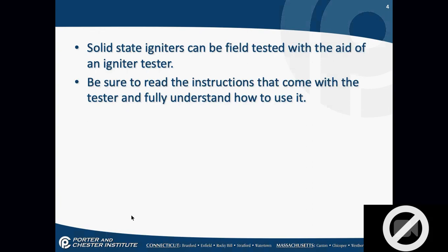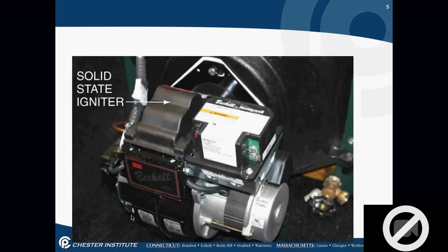So you don't want to use your meter on a 10,000 volt transformer. Bad things happen. Don't do it. Your meter leads are not rated for that much voltage, and you also have to be careful of amperage on your meter leads. Always look at the manual that comes with your meter. It's always nice to know, because sooner or later, you're going to come across a 720 volt rooftop unit. Some of the newer meters might have 800 volts. But again, be careful.